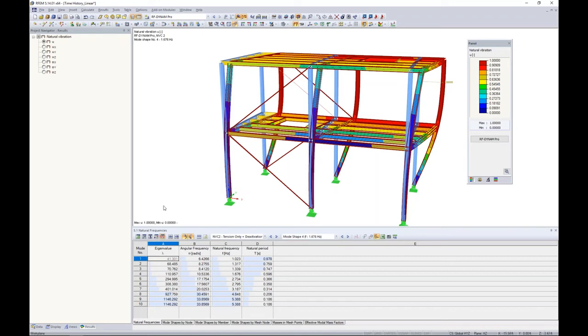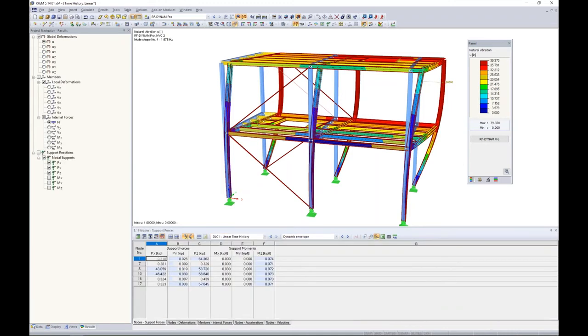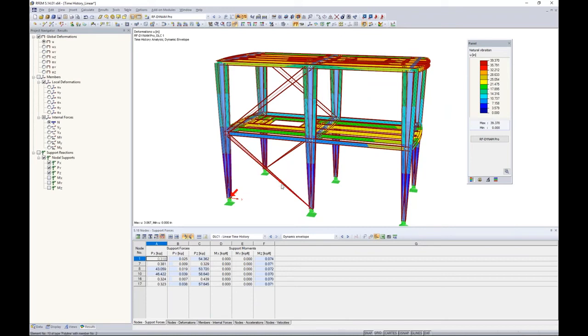So you might think, okay, let's jump back and just do another linear time history analysis, but we can't. If we take a look at our dynamic load case 1, linear time history, nothing's changed here. That's because those tension-only members are still being replaced by truss members. We're still going to see resonance because we don't even need a natural vibration case for this particular solver. They're not related whatsoever. So what we do need to do is to move on to a nonlinear time history